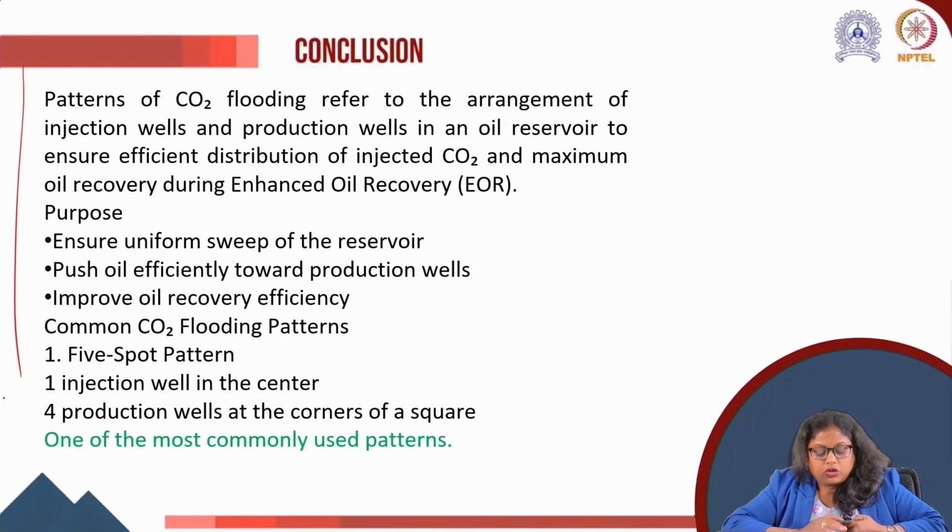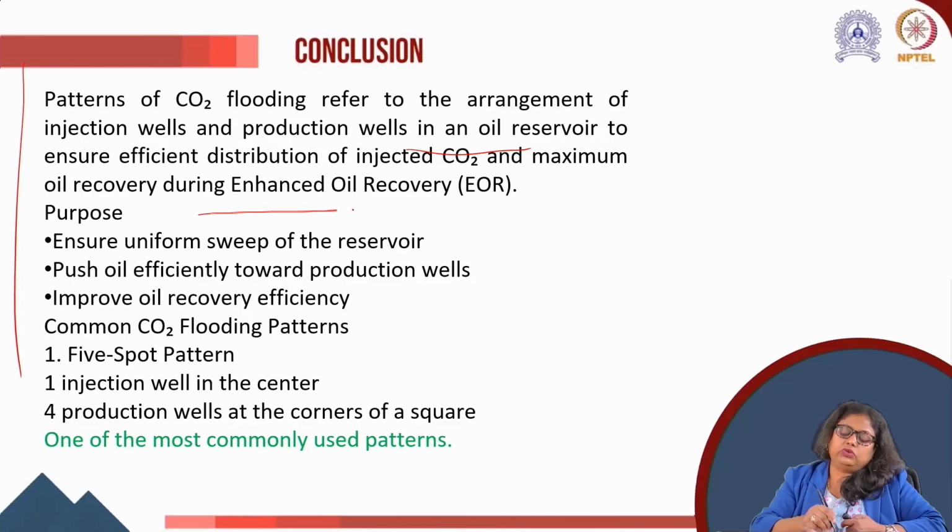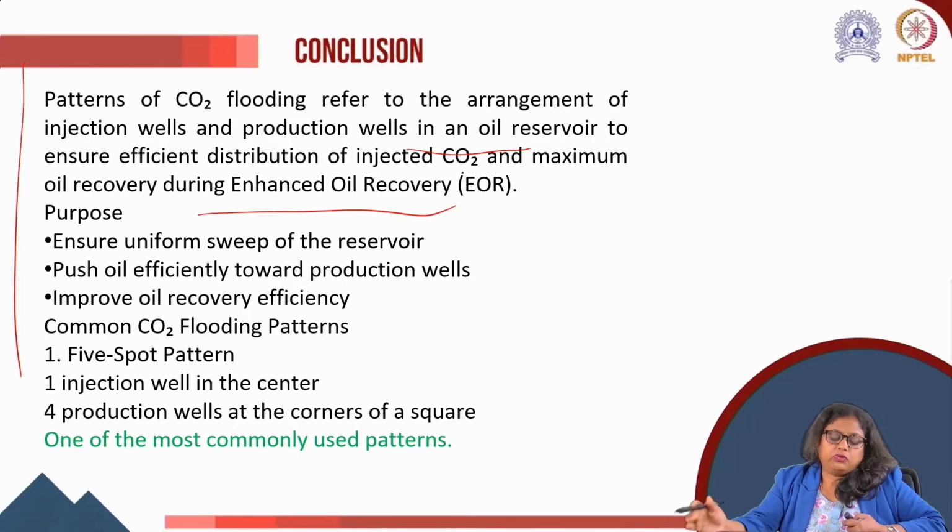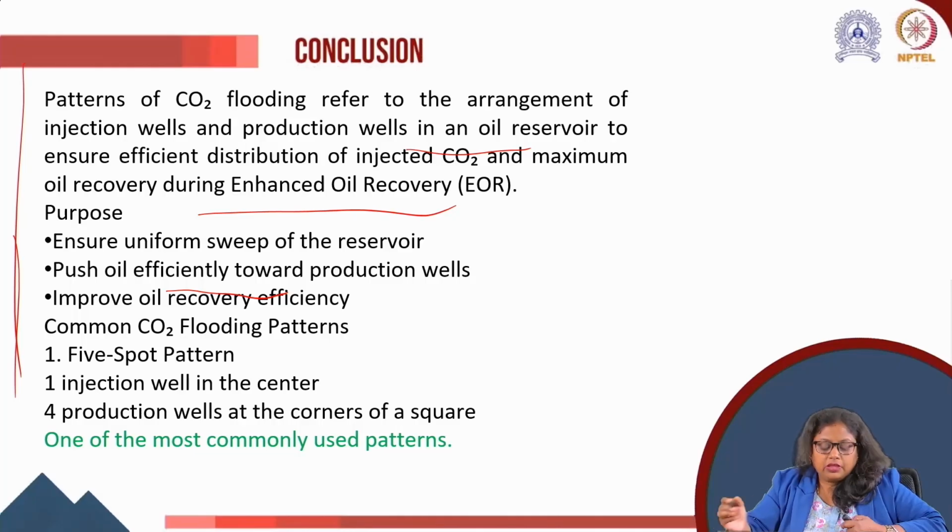And then we talked about some injection patterns. The pattern of a CO2 flooding refers to the arrangement of injection wells and production wells in an oil reservoir to ensure efficient distribution of injected CO2 and maximum oil recovery during your EOR process. The purpose is to ensure uniform sweep of the reservoir, push oil efficiently towards production wells, and improve oil recovery efficiency.